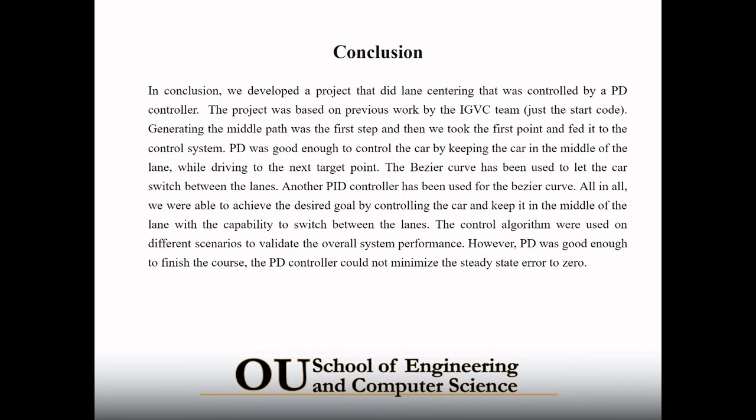So in conclusion, we developed a project that used lane centering, and the car was able to drive in the middle of the lane using a PD controller. We started by taking the IGVC course startup code, and then we started generating the middle centered lane that the car needs to follow. And then we added a PID controller to make sure that the car stays in the middle of the lane.